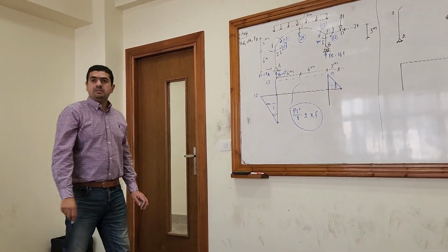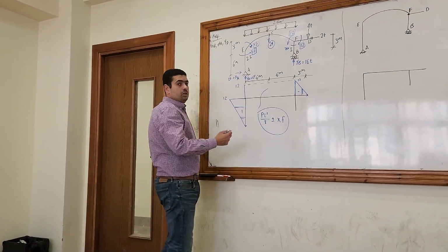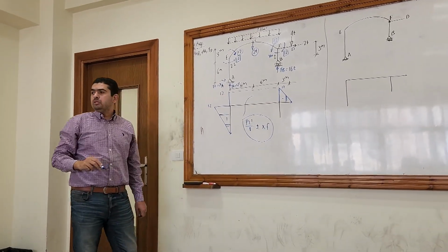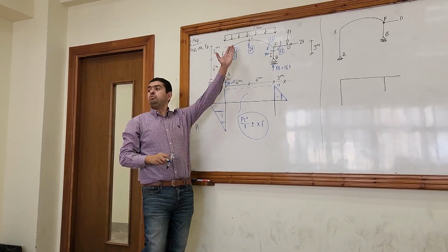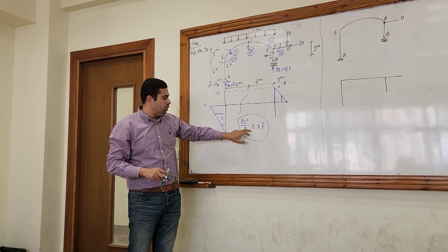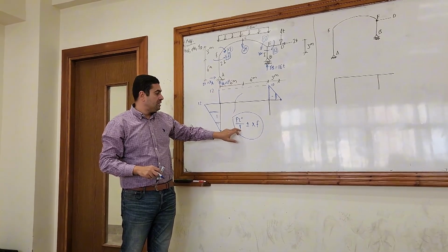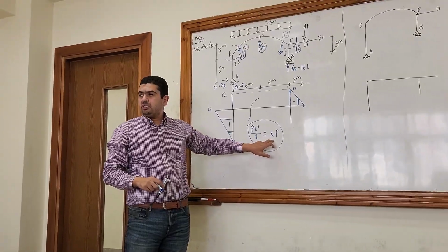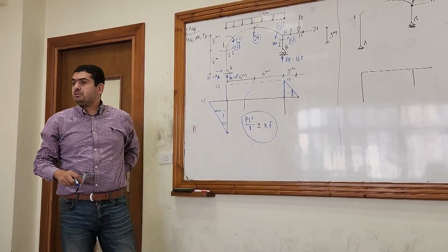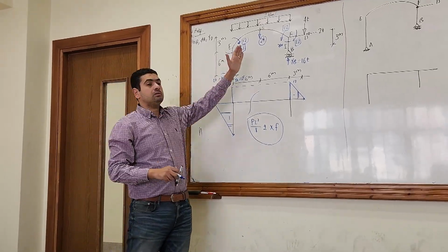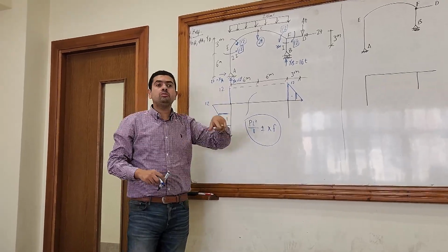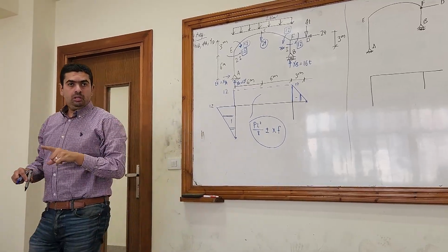So that means the arch can be a parabola in the bending moment diagram without any loads, without any distributed load, because the effect is not only from the loads, there is an effect for the arch itself. So don't be surprised if there is not any distributed load on the arch, and you also draw in the bending moment a second degree parabola. Okay?